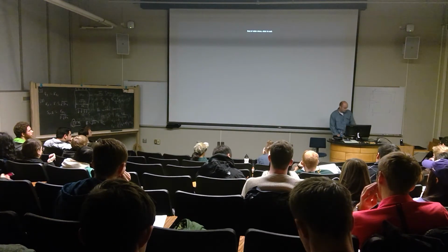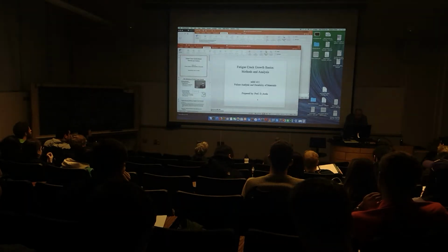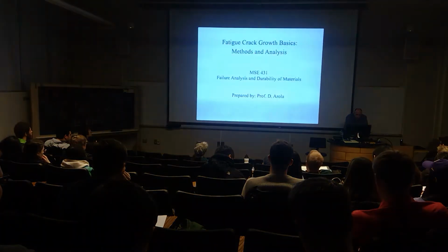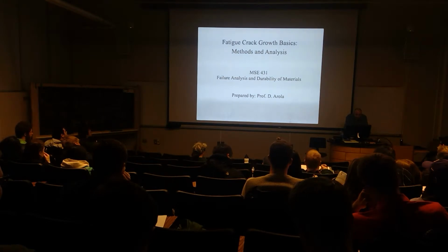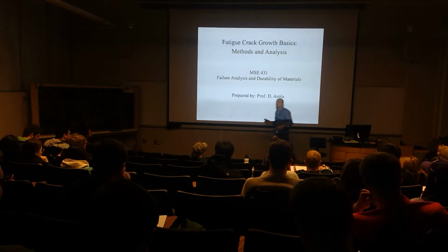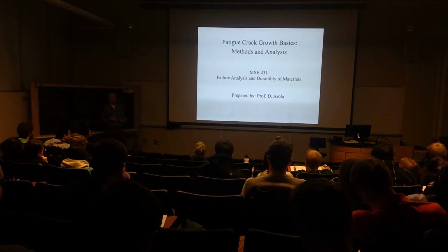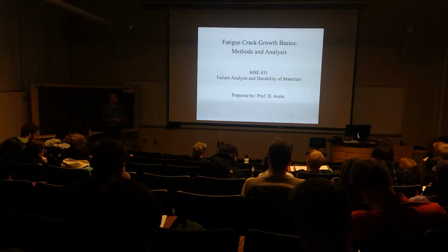Great. So, now, we start talking about flaws in terms of when they're going to contribute to fracture. So let's say, for example, that we have a flaw within a structure and it's not quite critical. It sits there. Can we forget it? It means the structure is going to fail by yielding for us. We don't want to forget it because what can happen is it can grow. So we want to know how long will it take, or was that fatigue crack growth process really something that could contribute?